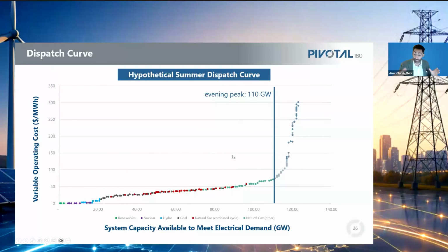I just wanted to illustrate that the supply stack isn't fixed. It obviously changes if a resource becomes unavailable. Everything moves to the left or right, depending on where that resource in the supply stack and merit order is lost. But now we have to activate all these other power plants. So this power plant, which say has an average price of 75, if we were to go across in a straight-ish line, notwithstanding my shaky fingers, that's the price it needs to meet its variable operating costs and incentivize all these other plants that previously went on to run.